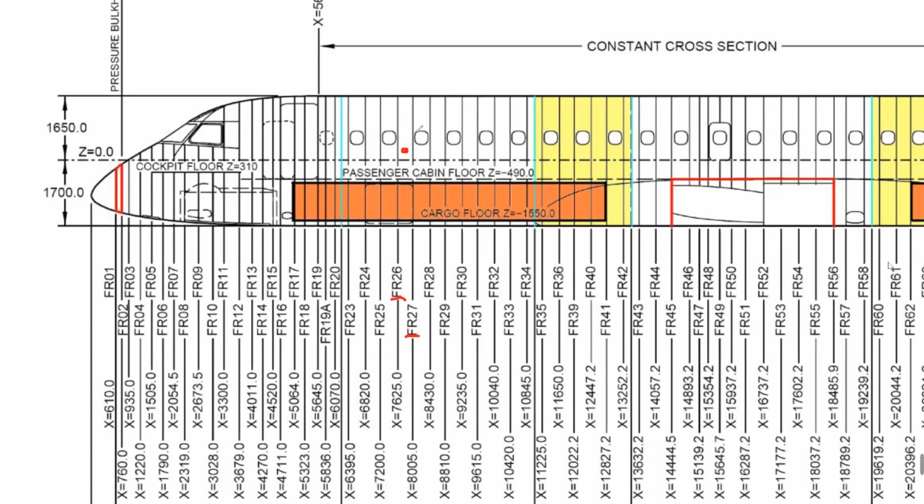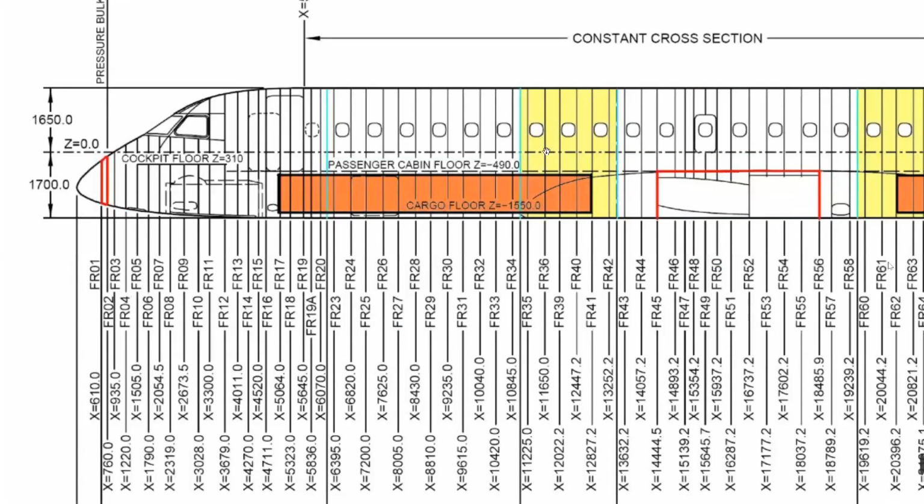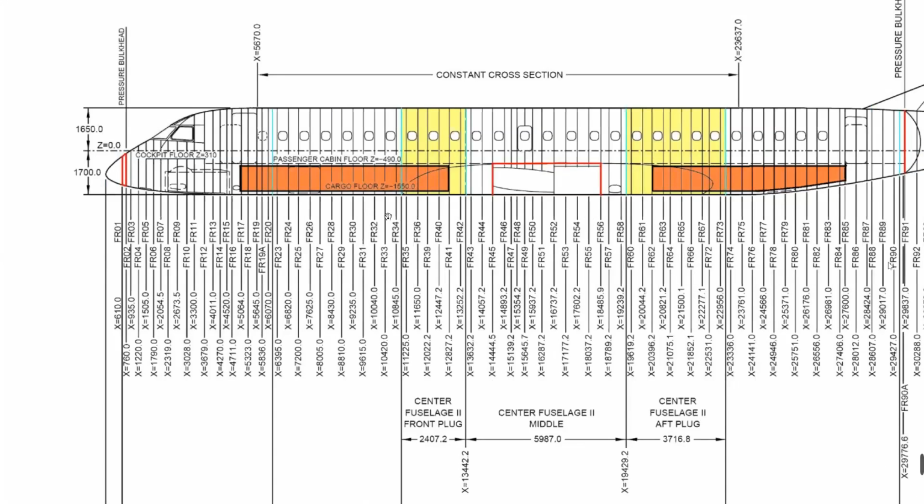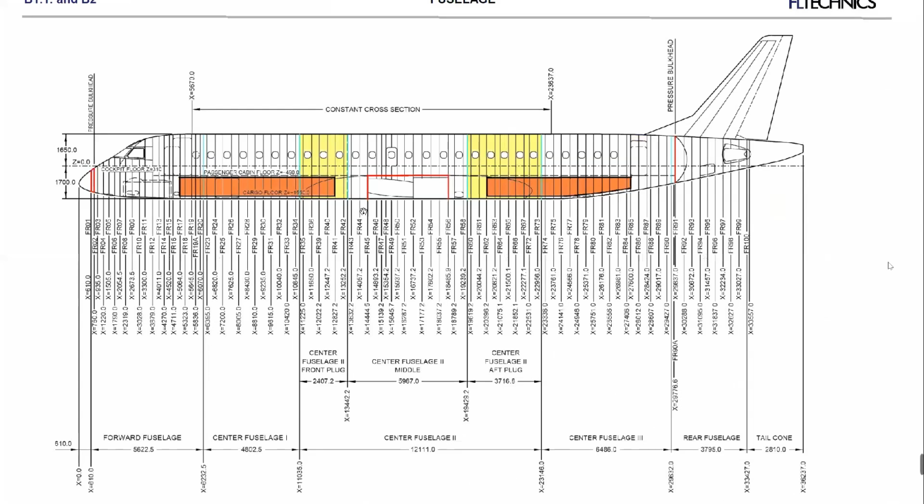Do you understand what I mean? Or if your damage is here, of course, no need to start from the first frame. Just have a look. We have this escape hatch, which is between these frames. So one window behind, I can easily find the frames by using a reference point. This is to reduce the possibility of mistakes when you're finding some location.